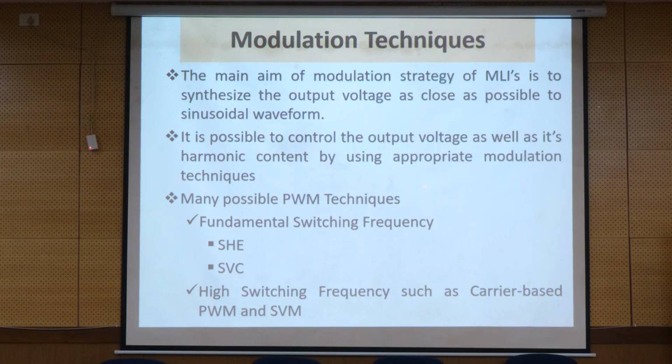There are many possible PWM techniques. For example, based on the fundamental switching frequency, we have space vector control and selective harmonic elimination, and for higher switching frequency, we are going to employ the carrier based PWM technique and the space vector modulation.